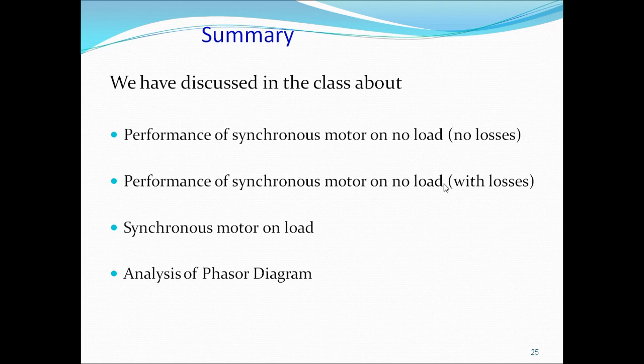So when load increases, alpha, that is the load angle, increases. When the load angle increases, the resultant voltage ER increases. When ER increases, the armature current drawn increases. This increased armature current produces more torque, and this torque supplies the increased load.